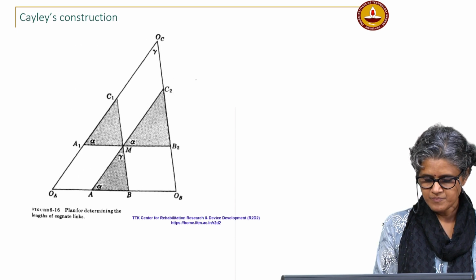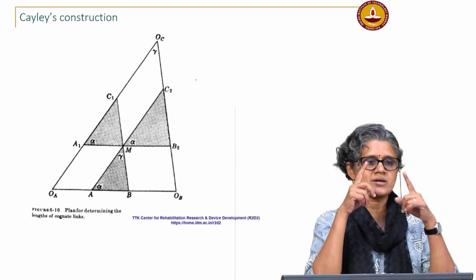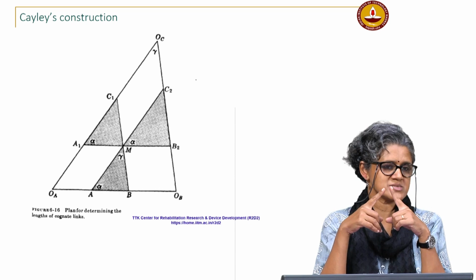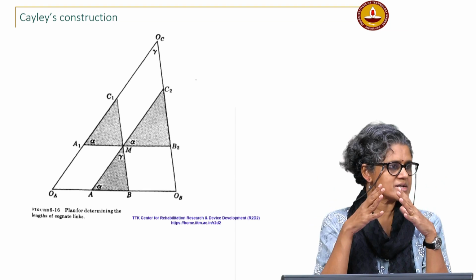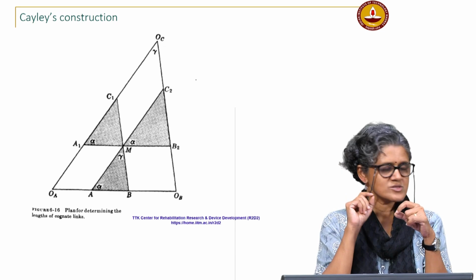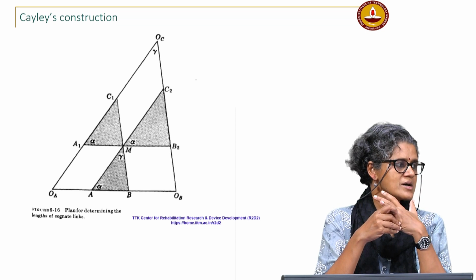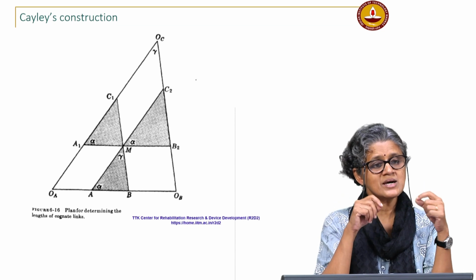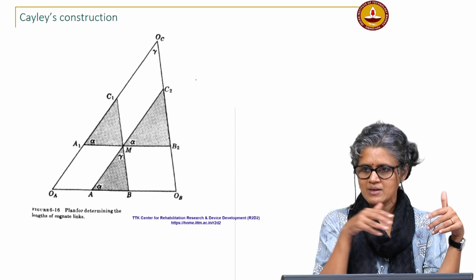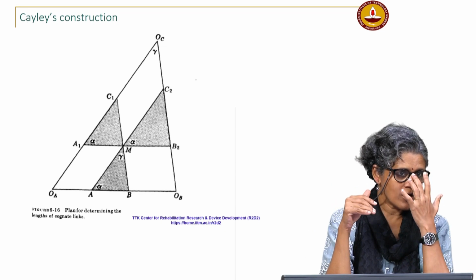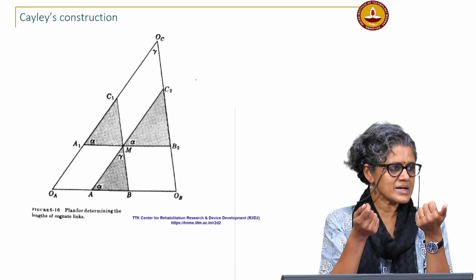Cayley came up with, so you can locate OC from the Roberts-Chebyshev theorem, right, by just constructing the triangle that is similar to the coupler triangle. So, the location of OC is immediately determined. Cayley came up with a different method for determining the link lengths of the other two linkages. So, instead of doing the parallelogram construction, this is a simpler construction to determine the link lengths.